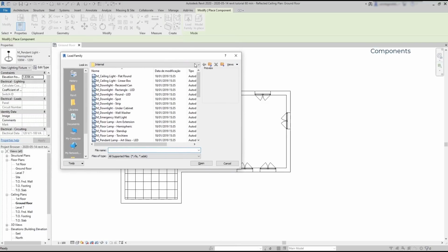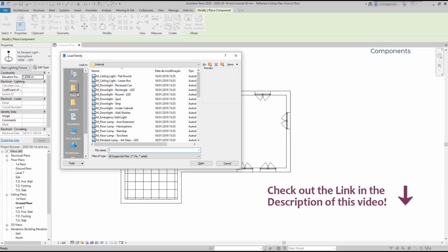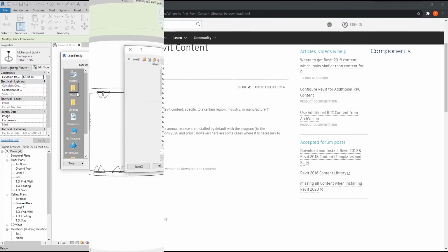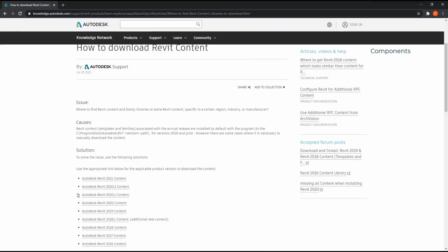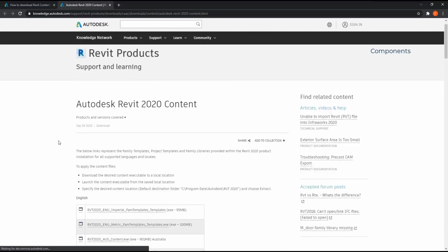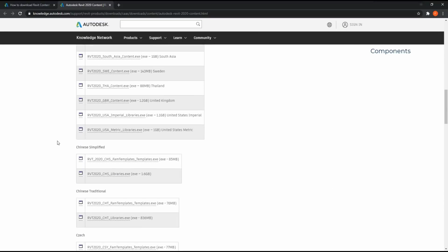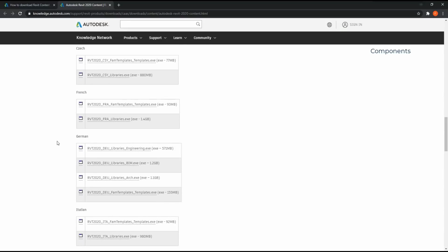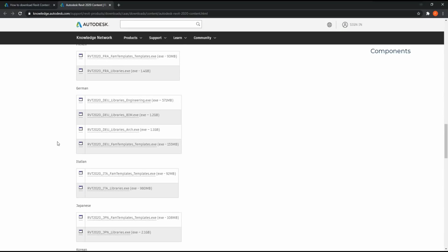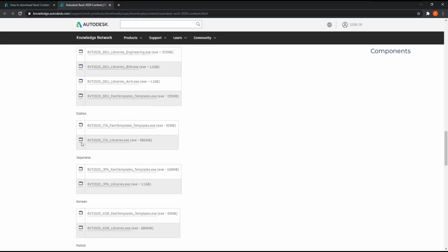It's highly recommendable to download the family libraries if you haven't installed them on your computer. I added the link in the description of this video. Click there to access the Autodesk website where you can find the libraries. First, click on your Revit version, search for your language or country, and then install it. They are grouped by languages, countries, or even whether they use metric or imperial units. But make sure you click on a library.exe file, like this one, and you will have a very complete library.